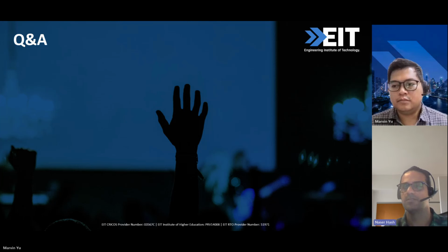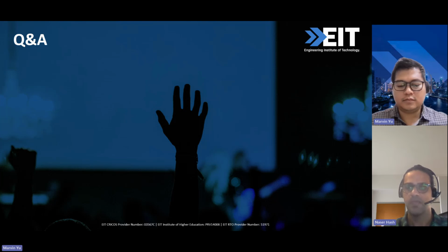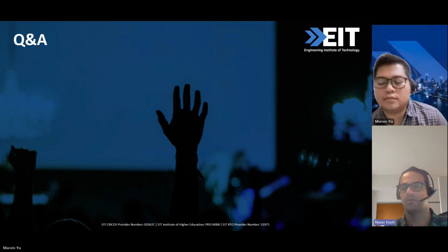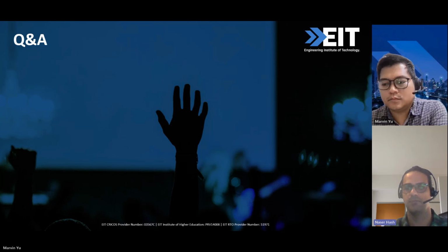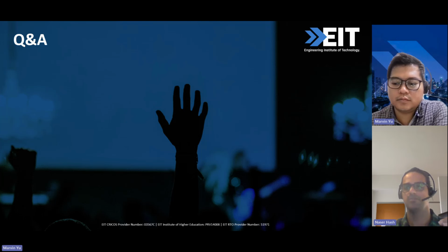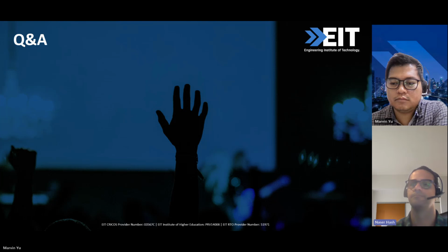But I recommend you search on Google for the DNO, distribution network operation, framework. I think it's open source. You can download it and go through it and see how the health index is calculated, and how the probability of failure is calculated based on the observed and measured parameters that you collect from your assets or from the OEM.